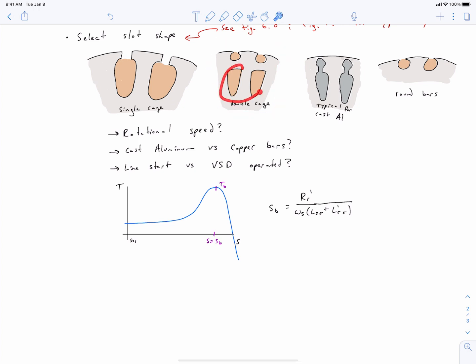So in this rotor over here, at high values of slip, so say that your rotor is locked, you're going to see the maximum frequency of field going through your rotor, right? The frequency of the rotor field is just going to be equal to your stator's synchronous frequency or the frequency of your air gap field. And in that situation, your leakage inductance creates a high impedance. So these inner bars in here have high leakage inductance because there's a steel path for flux to flow. So these are going to inherently be very high leakage inductance conductors.